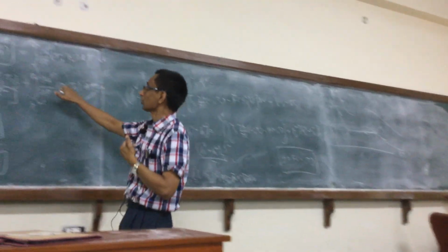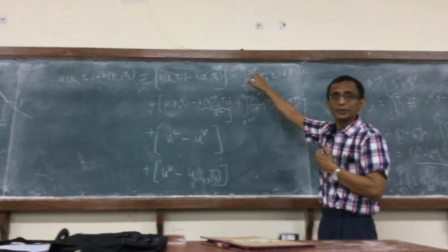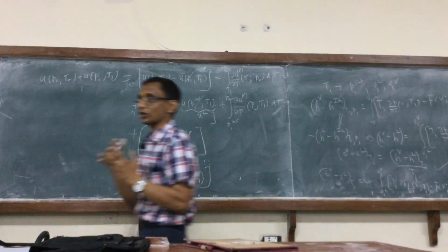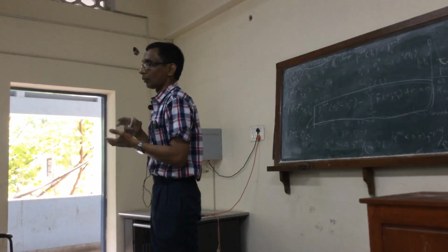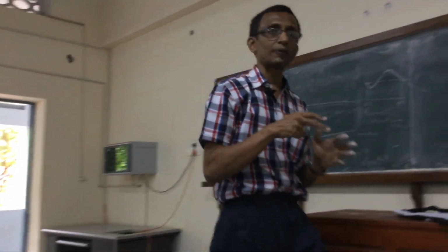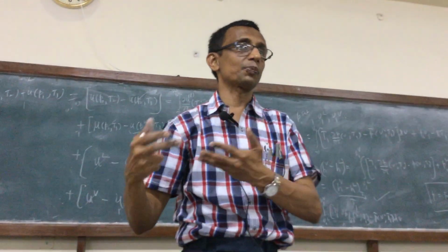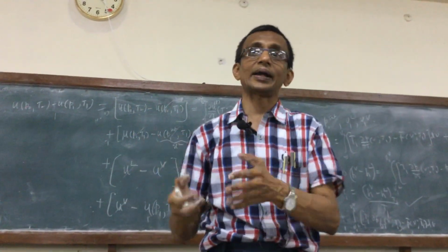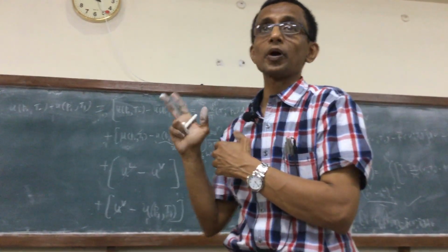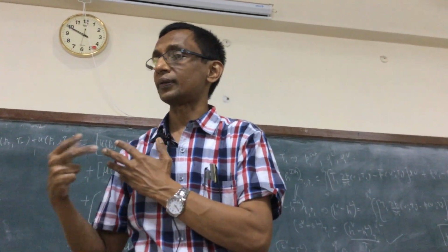So this I can get, but for this I need specific heat data. It's important to remember that it is liquid, because for instance specific heats of liquid do not change that much with pressure. It's important, that's a physical fact that you have to be aware of. Certain properties of the liquid in general, it's a good rule of thumb that liquid properties do not change significantly with pressure. So that will be very useful if you have specific heat data at some nearby pressure, that would be sufficient. You don't exactly have to have it at P2. So it's important to keep in mind the distinction in the properties of the liquid phase versus the gas phase.